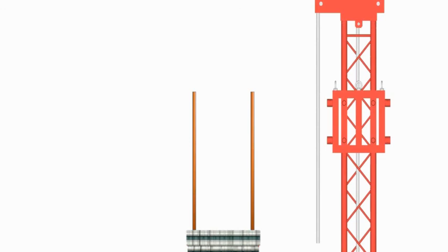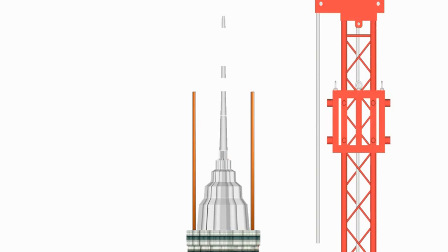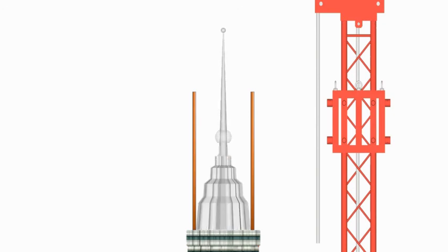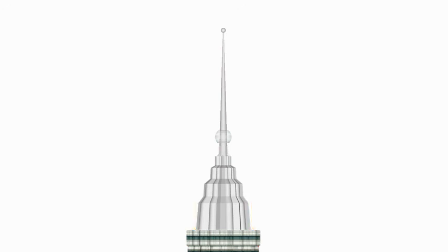The structure was raised to the position of the pinnacle using the jack-up method. The following structure was constructed on the ground, while connecting the existing and new structure with welding. In this way, the entire stainless steel part of the pinnacle was fixed to the mast anchor, and the jack-up system and guide rail were dismantled.